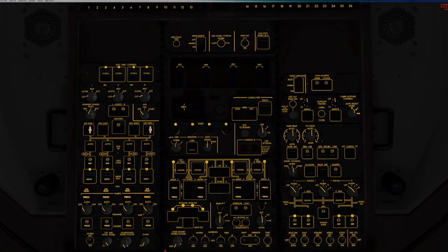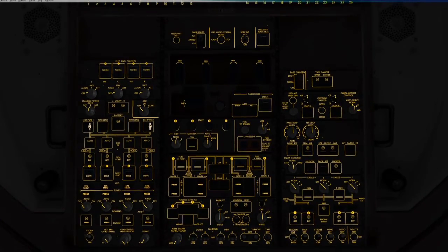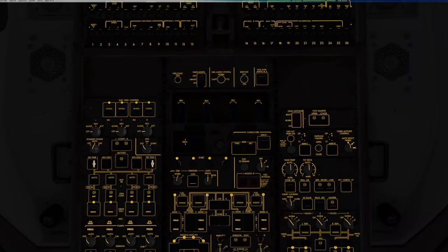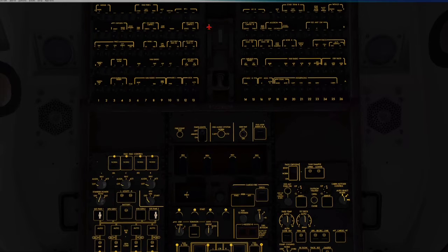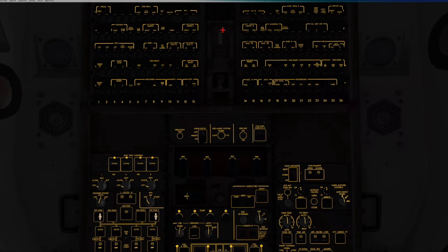The aisle stand, which is where the thrust levers are, and the radios, and weather radar, and all your audio control panels, all that stuff. This is the switch for that. Again, you've got an inner and an outer switch. The inner is the smaller switch, the outer is the bigger switch. The floodlights for that, if we scroll up a little bit, on the P7, above the smoke vent handle, you'll see right here, these are the floodlights for the aisle stand. This is what's going to come on when we turn on the floodlight.